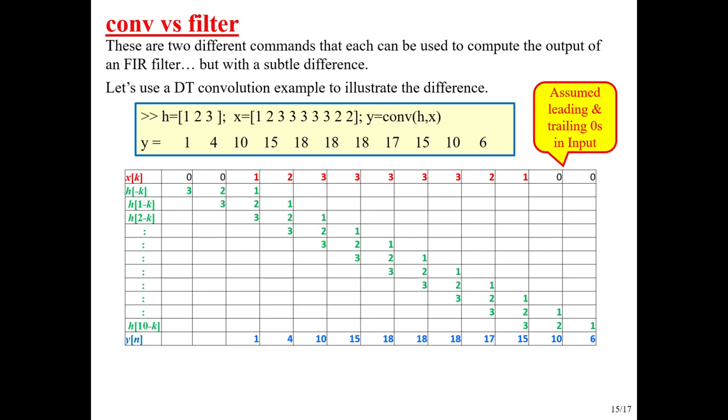So another way to think about that, kind of semi-graphically: I remember the convolution process is you take one of these, flip it. So here I am flipping it, and shift. You just keep shifting by 1. After each shift of the flipped one, you multiply it by the corresponding values in the input, add up those products, and spit that number out.